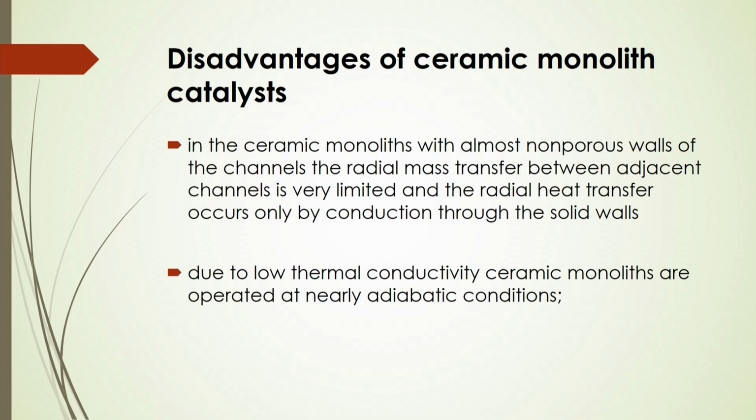But parallelly you will get some disadvantages of monolithic catalysts. If you have a ceramic monolith, with almost non-porous channel walls, the radial mass transfer between adjacent channels will be very limited, and radial heat transfer occurs only by conduction through the solid walls. In that case, it is not actually suitable for chemical engineering reactions. Due to the low thermal conductivity, ceramic monoliths are operated at nearly adiabatic conditions.